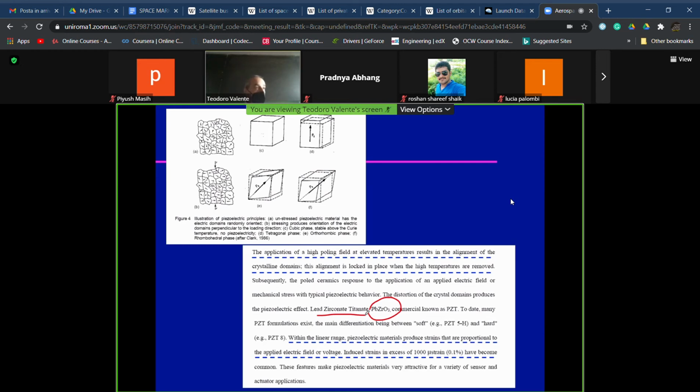So they have a very low value of fracture toughness, around some units of megapascal per square root meter, which does not allow the material to show a good tensile strength, due to the fact that defects always exist and can be easily propagated when we have a tensile stress field around the defects in brittle materials.